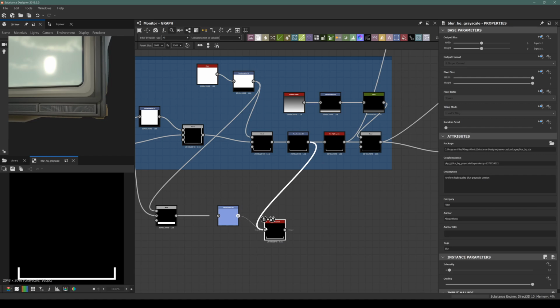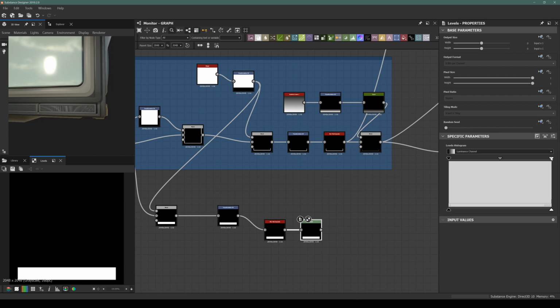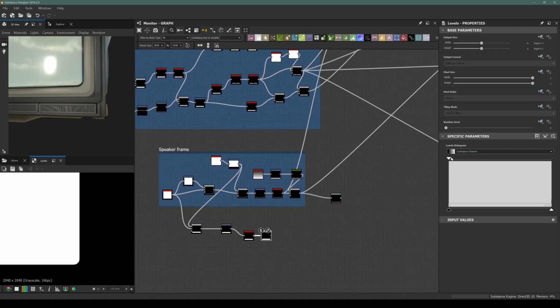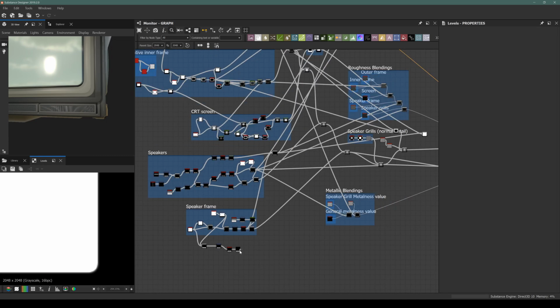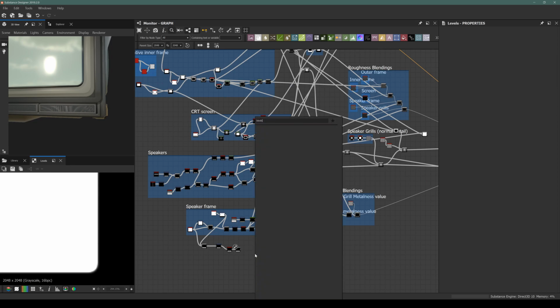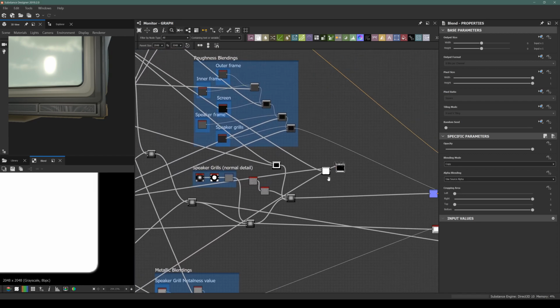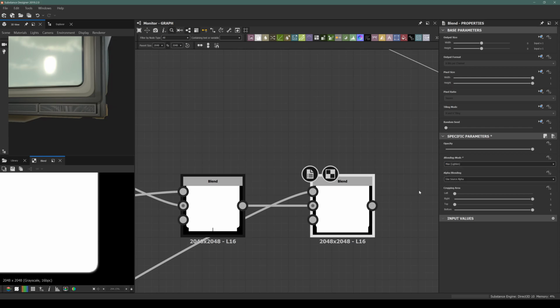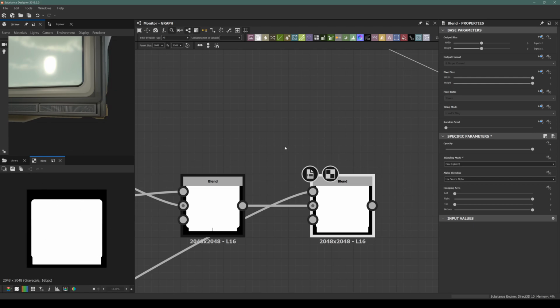Also we have a blur node which makes the corners on the bottom side like here. And then I will add a levels node to push the values down to all white. This way we have the rounded corners of the speaker shape. So I can add this as a blend in a blend node with the rest of our mask here with a max lighten option. This time we have the exact outer boundary of our shape.